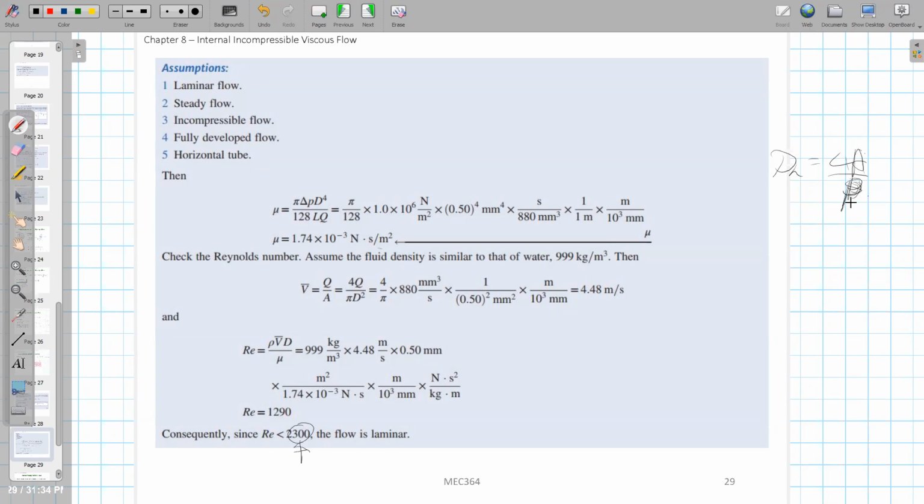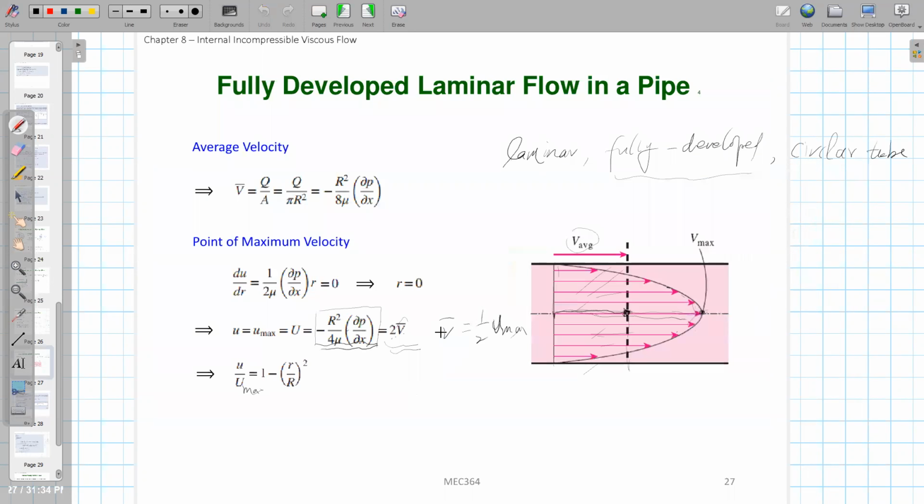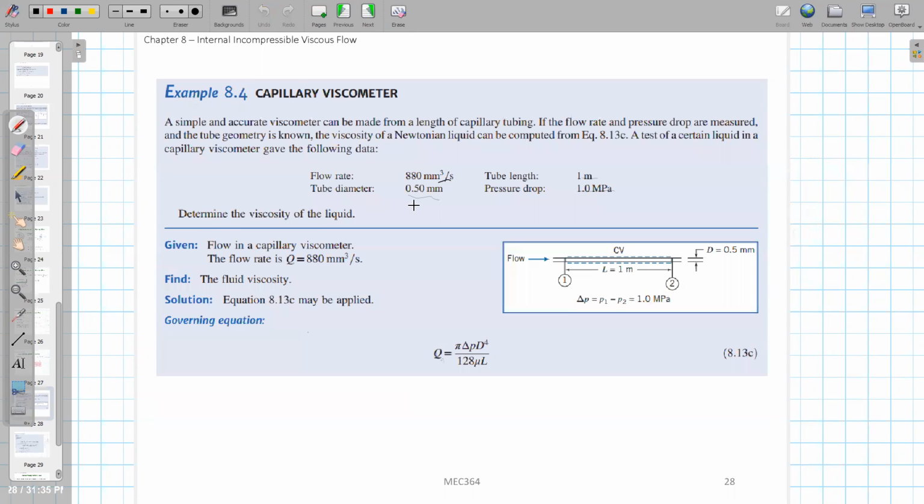The basic concept of the hydraulic diameter is that if you have a rectangular tube or triangular tube or whatever, you calculate the cross-sectional area for A. You calculate the wetted perimeter, meaning the perimeter the flow is in contact with. Calculate P, so you can calculate the equivalent diameter D_H, so that the flow problem will be equivalent to a circular tube problem with D_H, so that you can still use the equations we developed.